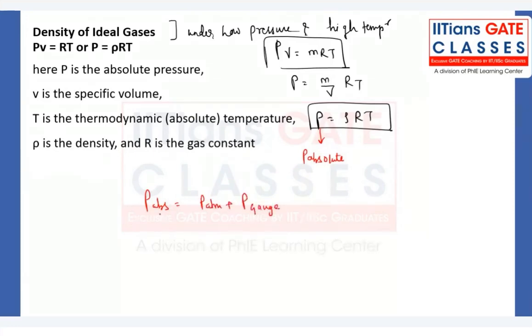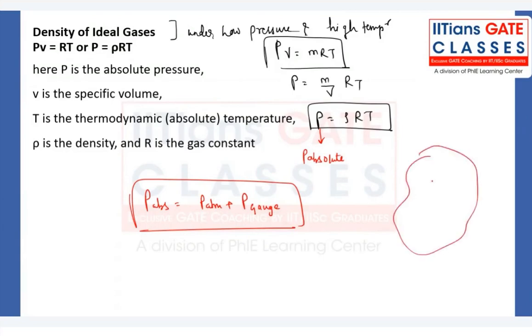In fluid statics, we will be learning the concept of types of pressure, right? In that we'll cover how many types of pressure there are: atmospheric pressure, gauge pressure, and absolute pressure. At any particular location, suppose you are living in this place, if I say that at this particular point the pressure is, let's say, 105 kilopascal, what is the meaning of that? Are we showing the atmospheric pressure, the gauge pressure, or the absolute pressure, that is, the total pressure?